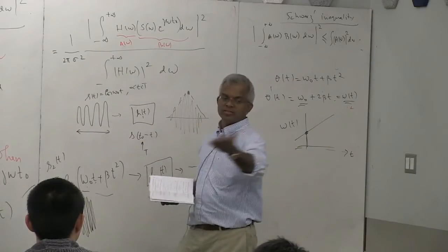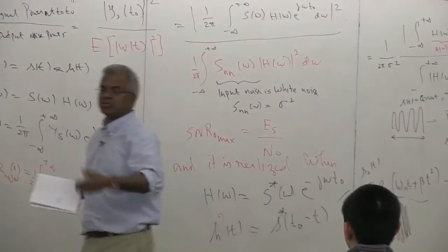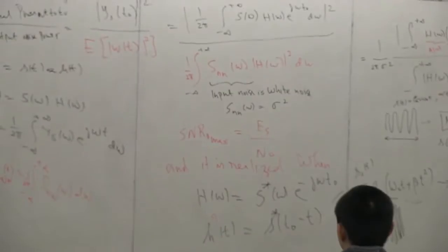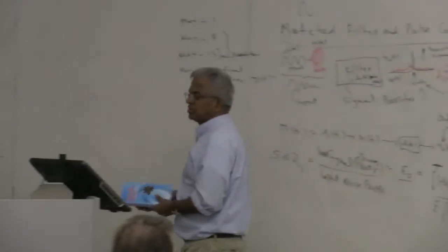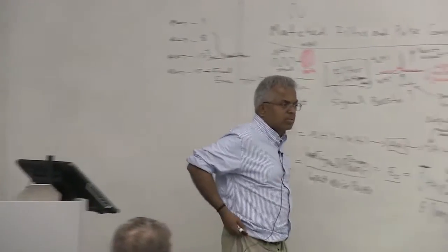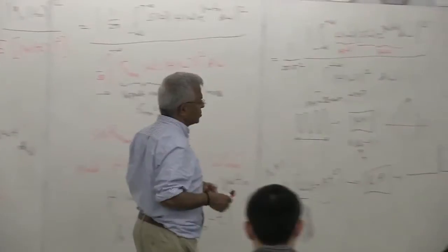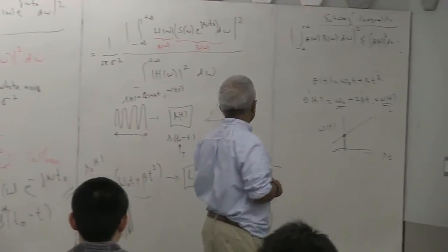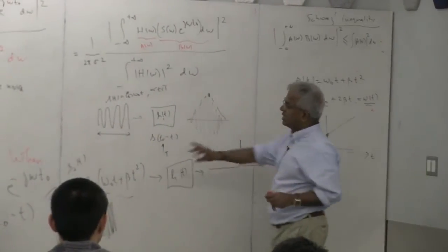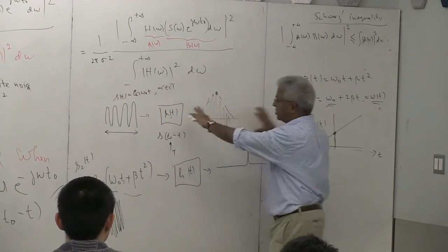So this is why I said, one way to get warmed up to this is you take the chirp signal, you just design its match filter, and simply plot it. You yourself can see the pulse compression properties. Then you can think about why this is true, and have some applications. You take any other signal and pass it through it, you are going to see this phenomenon. The pulse is going to spread out.